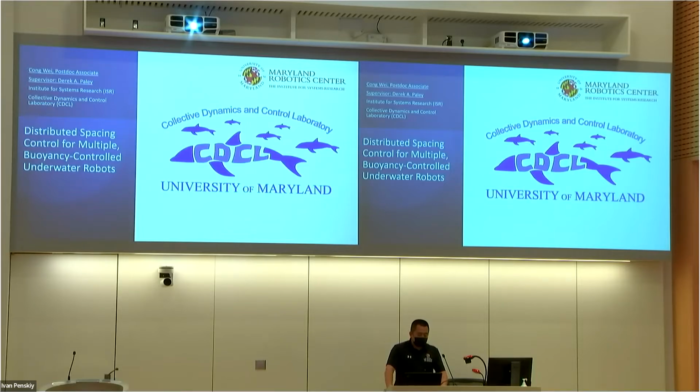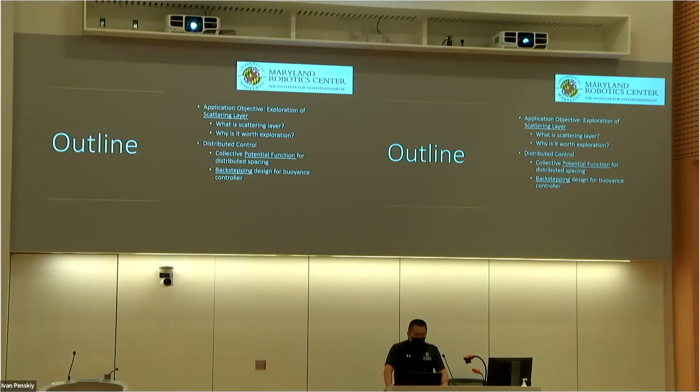My topic today is distributed spacing control for multiple buoyancy-controlled underwater robots. This research is the control part of our current work, which is finding a way for a distributed system to track and observe an underwater biology system named the scattering layer. Given the underwater flow velocity and the dynamics of the scattering layer, our distributed system can achieve desired formation while tracking the scattering layer by the control algorithm.